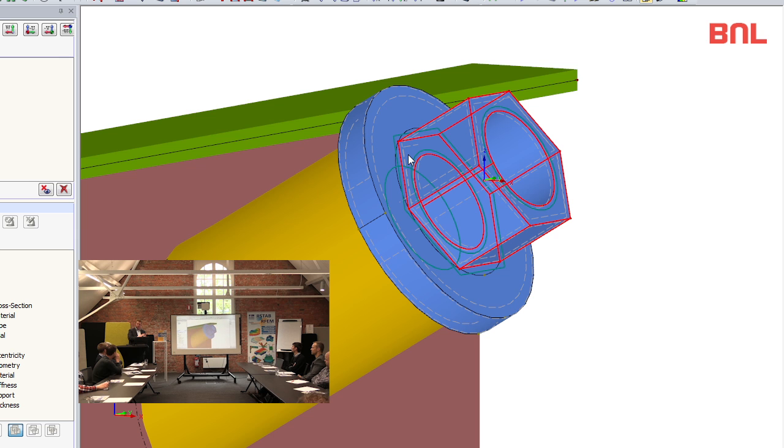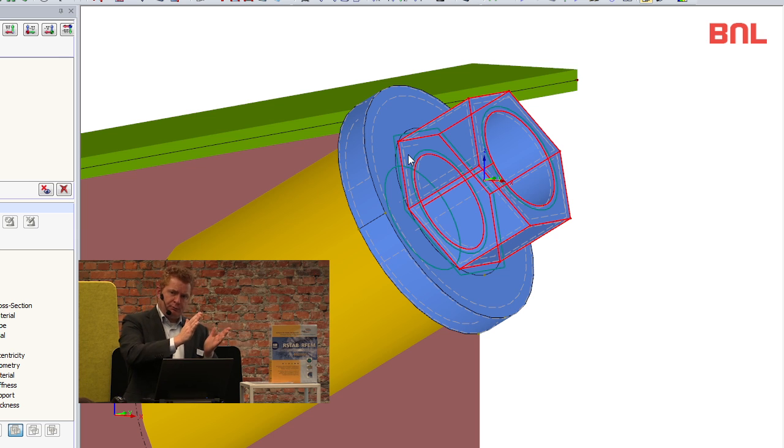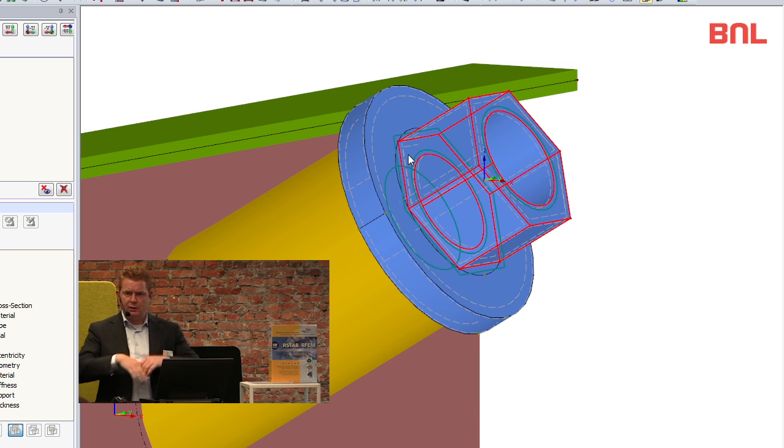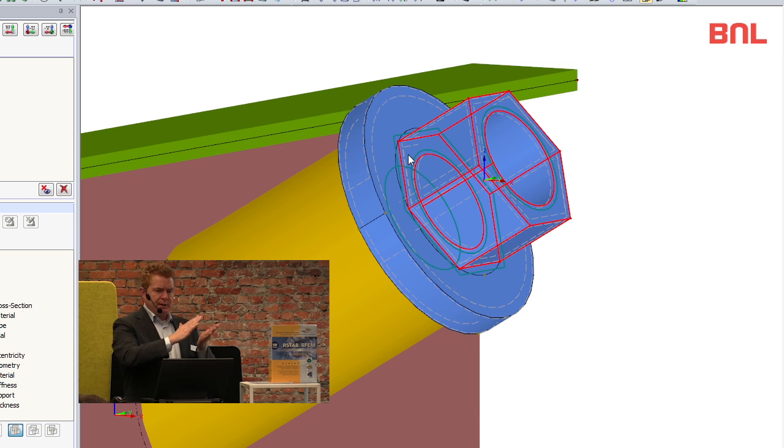It is automatic. If you want to model something like a contact that you really have pressure only, for instance, it's different. That's what Walter will handle, all this advanced stuff. But remember that if you have this case, if you place a solid on top of a solid and there's nothing special, it will share the same nodes and the same meshing, and then it's okay. Yeah?